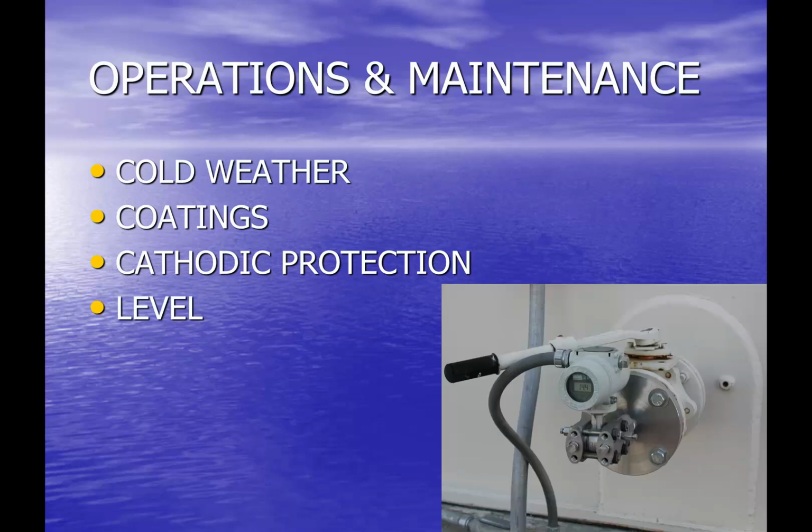below ground. We've talked before about level in reservoirs and the instrumentation associated with measuring level, and you see the same picture of a level transducer we've seen before that's providing a signal to the local PLC and ultimately to our SCADA system so that we know what the level is in that reservoir at any given time. We're also often evaluating what the volume is in reservoirs based on that level. We've got tables that tell you, okay, every foot is a certain amount of volume. It's pretty simple math. Once you know the level, you can pretty easily equate it to the volume